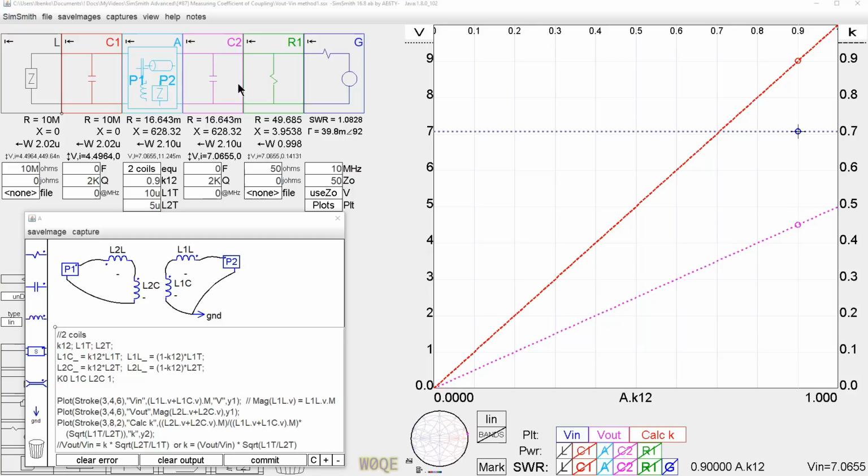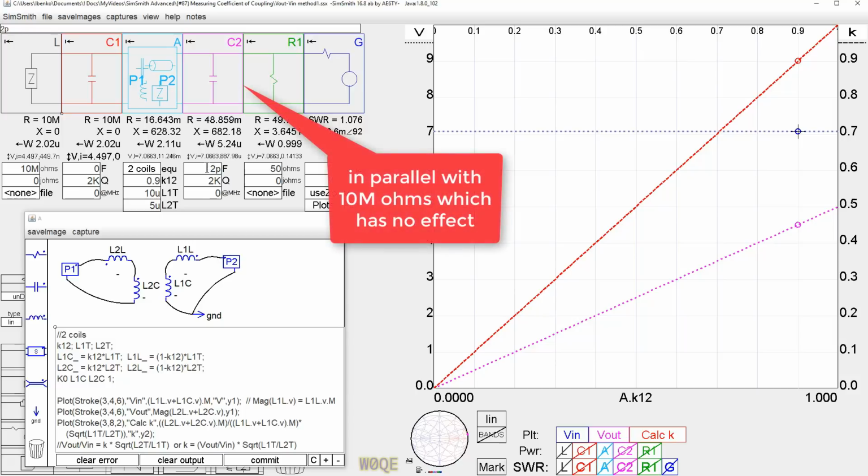Probes being different, but if I take channel 1 and put it across here and I measure voltage, and then take channel 1 and move it over to here and measure voltage, let's see what that means. Putting channel 1 here with a times 10 probe results in a couple of picofarads of capacitance. And that's okay. Let's see what the effect of that is.